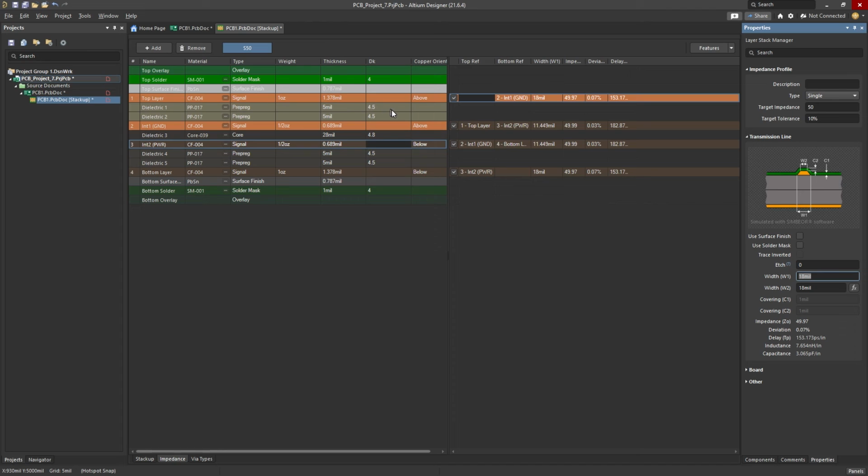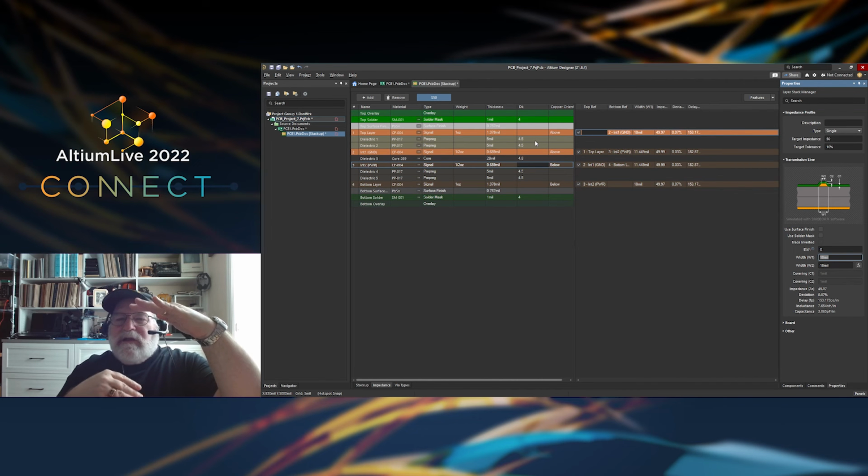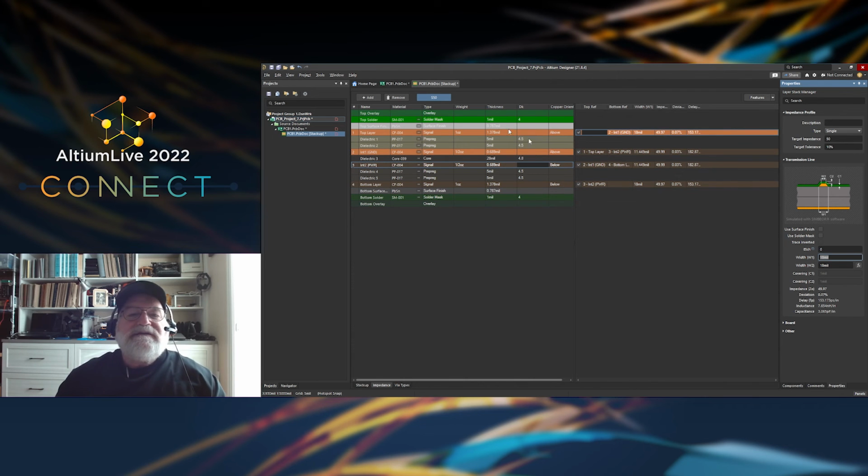Now if I make the dielectric thickness thicker, I pull the trace and the return farther away, what's going to happen to the characteristic impedance? Well, I should find if I pull the return farther away, I decrease the capacitance per length, and if the capacitance decreases, the impedance is going to go up. So let's make it thicker. I go from 5, make it 10 mils. Everything else stays the same. I should see a higher impedance. And sure enough, I made it 10 mils, higher impedance.